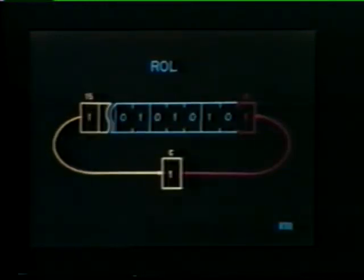The ROL, or rotate left instruction, does just that. Rotate left is another single operand instruction. Notice that in constructing the circular buffer, the C bit of the PSW is used as a link between bit 15 and bit 0 of the data word. When the rotate is executed, the value in bit 15 moves into the C bit, and the former contents of the C bit moves into the 0-bit position. We can therefore rotate the entire word one place to the left without losing any information.